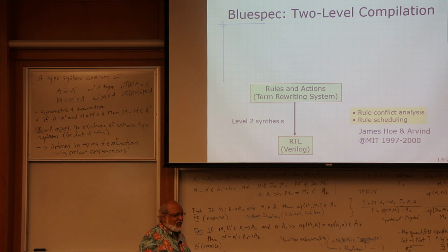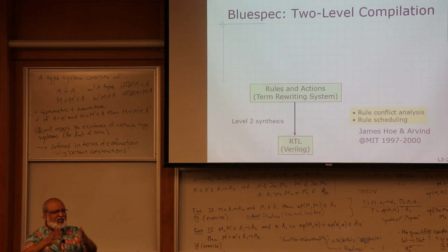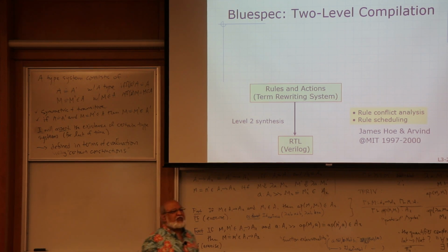So if I was building a programmable hardware machine, yes, it'll have many modules. It'll have an instruction fetch module, and it'll have caches, this, that. It'll have branch prediction. It'll have a reorder buffer. It'll have an ALU. It'll have a memory system. Each one of them will be designed, and my specification for that is not the programs that execute on it, but did I implement the ISA semantics correctly? You will generate the Verilog that describes the entire design.